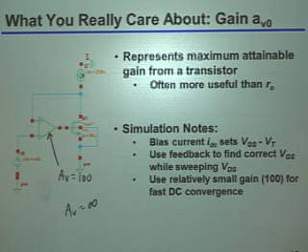is supposed to be. Okay, so the real point there is that you want to choose the gain in that op-amp high enough that you're confident in the accuracy of your results, but not so ridiculously high that you're just sitting there waiting for the simulation to try and calculate things well beyond the precision you actually care about. Okay? Does this make sense to everybody?